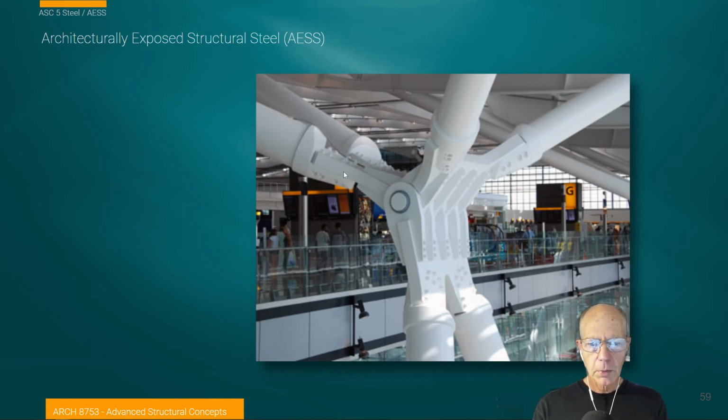So here we have a pin connection, a major amount of structural components coming together. The idea is that they're all either acting in tension or compression with each other, and we're really trying to deliver just those forces to our elements here. So we pin that connection together. A lot of forces are coming into that pin, and we're distributing those shear forces with each one of these little flanges that we have on here. There are multiple ones of them just to distribute that shear force across that pin.